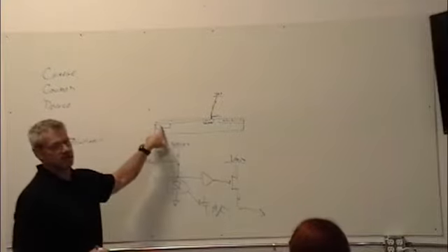What you would find is you'd have your imager, and maybe there'd be a bubble in it right here. Or if you're doing some of the mercury cadmium telluride, which is a very popular one for mid-wave and long wave, call it 3 or 4 microns out to 14 or 15 microns, usually this bump is indium.